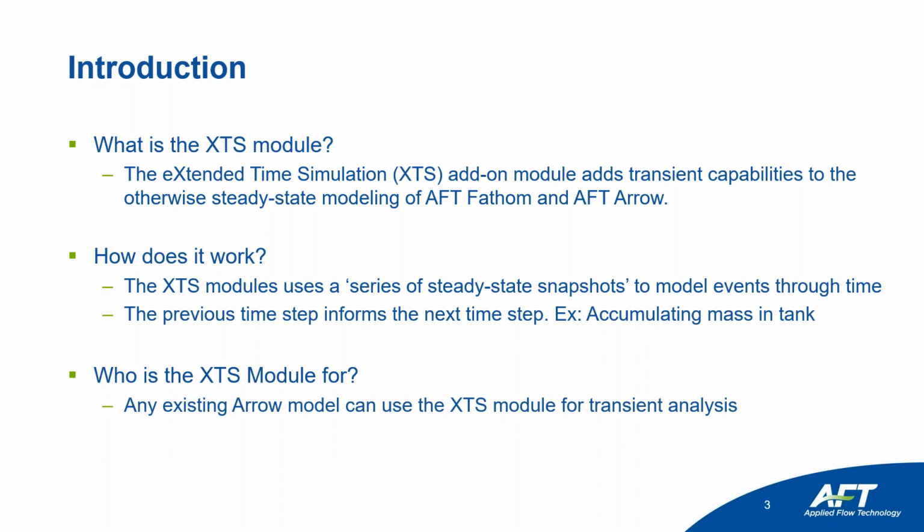Because it's an add-on module on top of these base products, you can apply it to any existing Arrow model and by extension, any existing Fathom model. And you can apply the XTS module to start your transient analysis. So it's not necessarily a replacement to that steady state analysis. Again, I imagine the majority of your systems are going to be operating at steady state, especially if you're in process. And so starting from that steady state basis where you're going to do the majority of your work, then you can turn on the module, access those transient capabilities, and then perform your transient analysis.